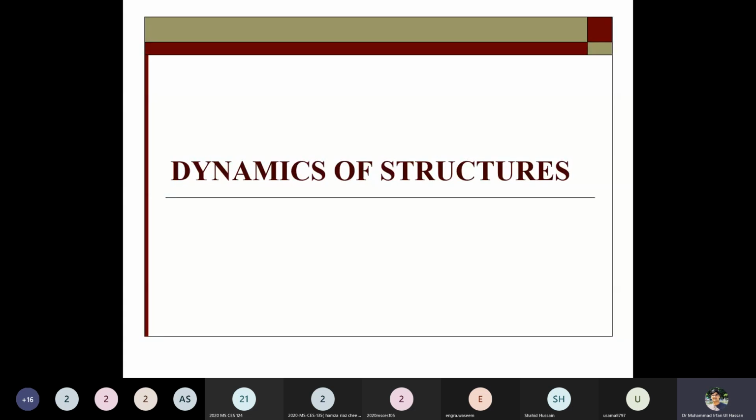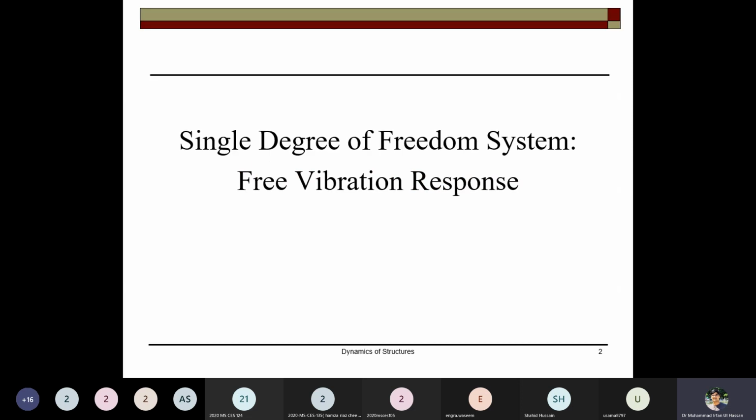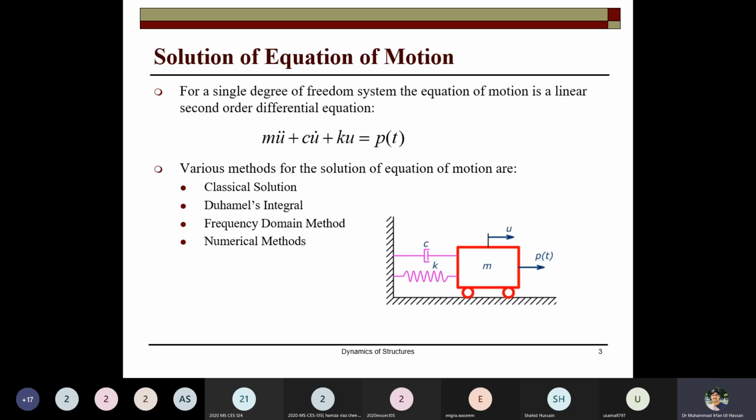You know that when any structure is initially displaced, studying the response of the system after that vibration is important, because this is also applied in civil engineering. Sometimes the force is continued, but when the force is stopped or once the initial displacement is already made, you want to see what happens if you displace the structure initially and how it behaves. So in this case, we are discussing the response of the system subjected to free vibrations.